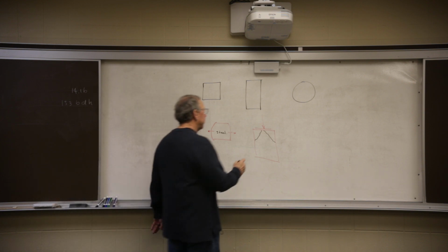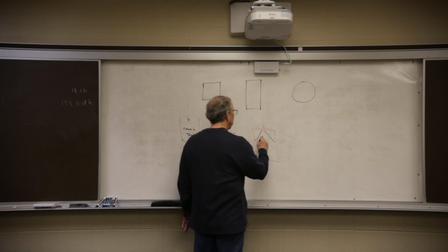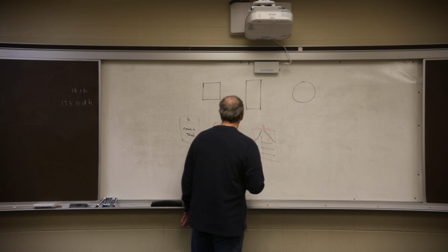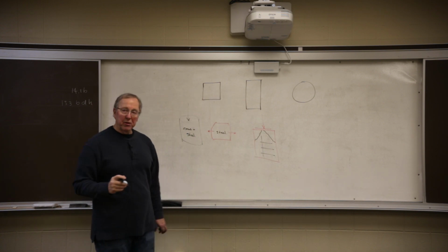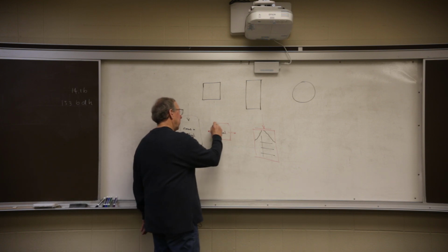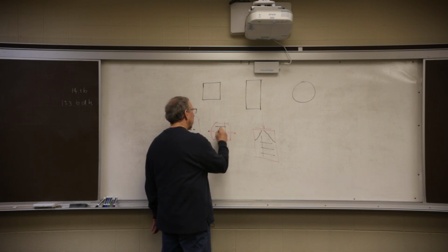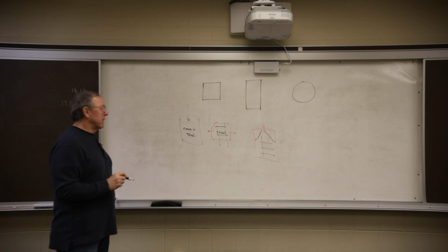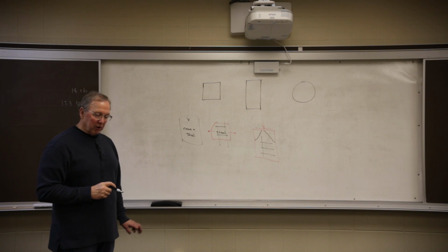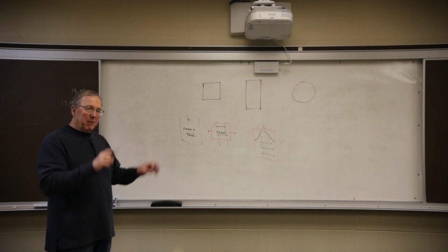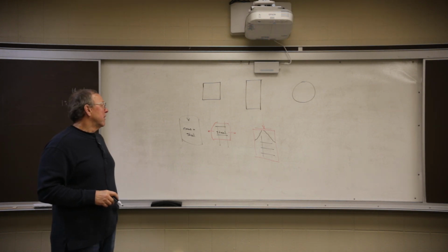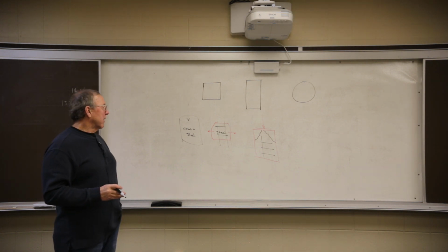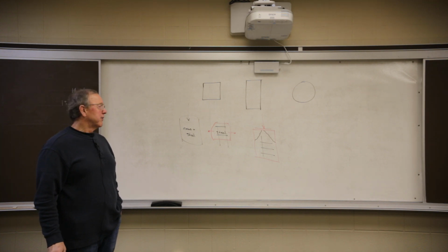And this, of course, shear has two. And if you look at it, the steel here, I'm talking about both components, the vertical and the horizontal. So the bars are going to be vertical, but it's also going to have a cage that goes around it that we tie the bars to so they stay in position. That cage acts as a tying device, and also it takes out the horizontal loads or thrust.